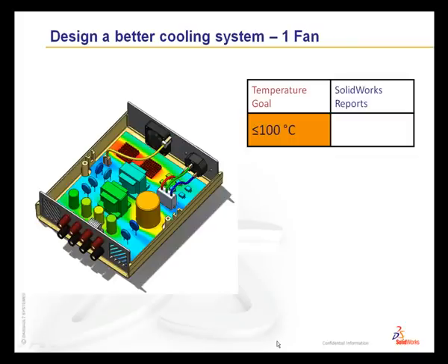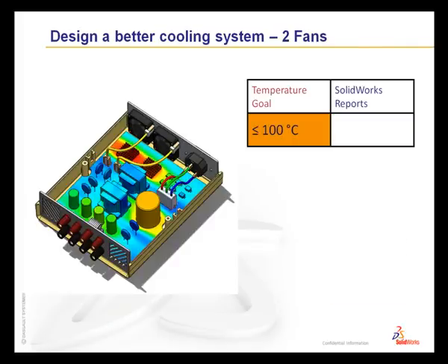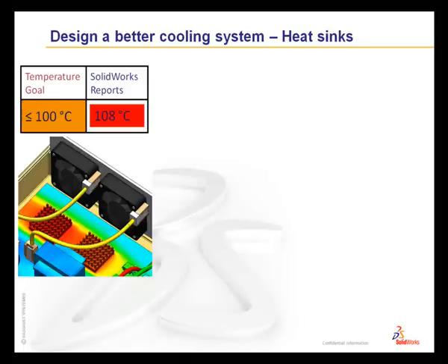In our example here, we saw that the original heat sink and one fan design did not remove sufficient heat from the CPUs. Running the model again with a second fan acts to reduce the temperature further as expected, but the study still shows a maximum temperature exceeding 100 degrees C. At this point we cannot add more fans, so we might try a different heatsink design.